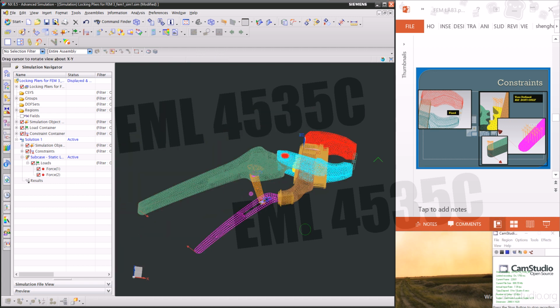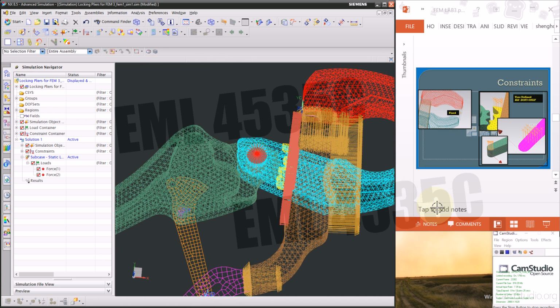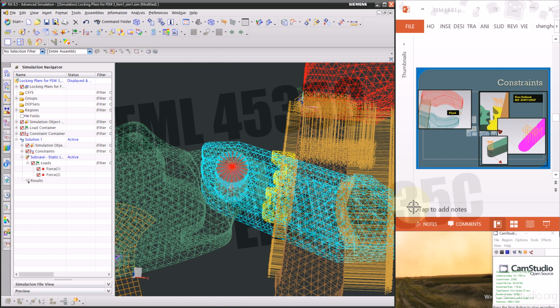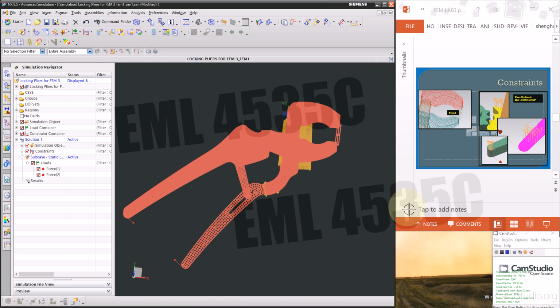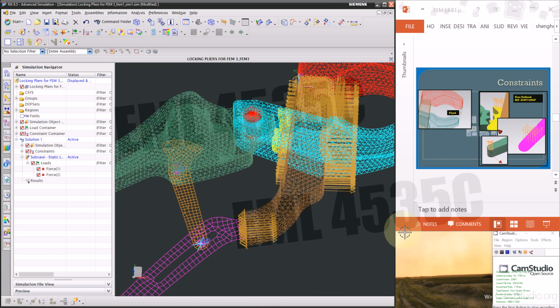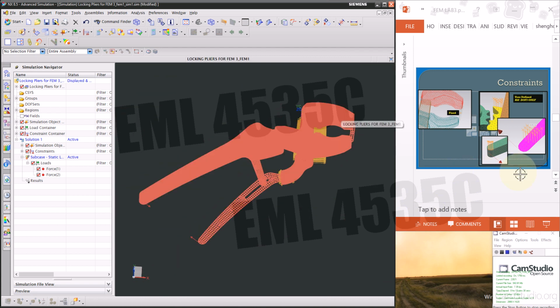So how do we stop it from rotating on 4, 5, 6? This is fixed, and these can rotate. That means these can rotate on the C-bar. So we just kill the Z direction on this structure, on the handles and this little block, because this little block has no contact to the other meshes. It only has a ball joint, which will not stop rotating anyway.